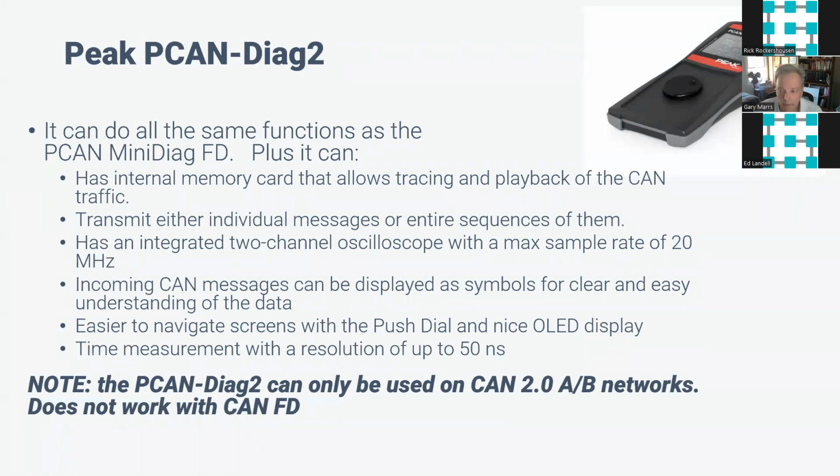It can record and data log incoming CAN messages, and you can even apply filtering on CAN ID to just capture the packets you're interested in. Captured messages can be saved, exported, converted, and viewed by other tools if you like. For testing, you can transmit individual CAN messages, or even transmit captured frame lists.